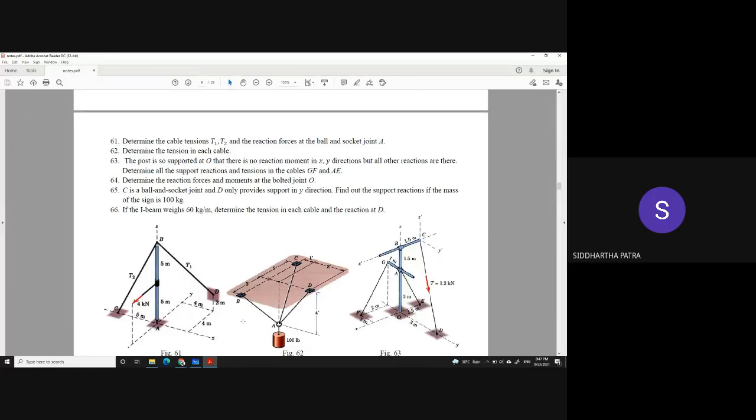I mean, you could also try to get the equivalent force system about B. There you should also consider the reaction forces coming from A. So you'd be trying to replace the reaction forces from A to B, and for that you need to do the moment correction and whatever we have discussed for the equivalent force system. So get the equivalent force system about any point, and equate them to 0. Once that is equated to 0, you can solve for your unknowns.